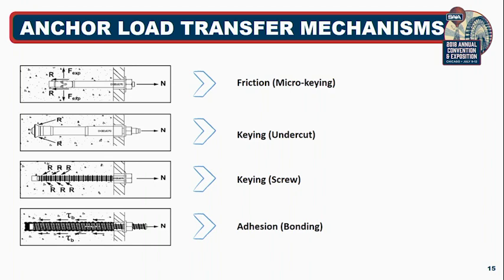You get the wedges over here, the anchor is installed, there's an expansion cone. When that anchor is torqued down, what happens is the wedges ride over that expansion cone, generate expansion forces, and it utilizes friction to resist the loads. Similarly, with displacement-controlled anchors like drop-in shell-type anchors, they utilize friction to transfer their tension stresses.